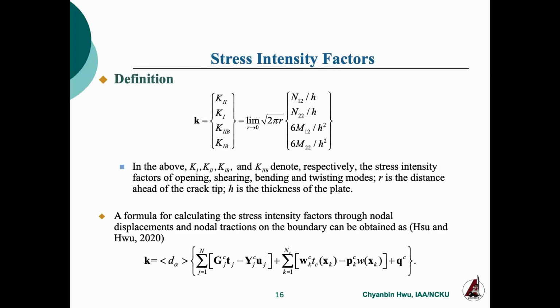And our target is fracture analysis. So based upon the definition of the stress intensity factor, we consider the opening, shearing, bending, and twisting modes, because we consider the mixed-mode fracture problem. So this is their definition. And this is the in-plane force. This is a bending moment. This is a twisting moment. This is the bending moment. R here is the distance ahead of the crack tip.